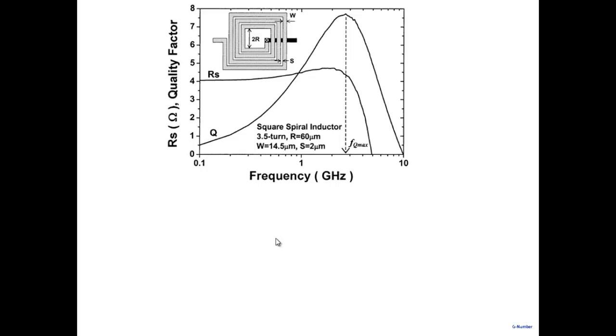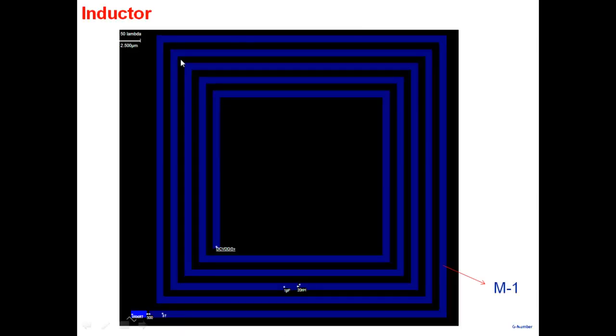Now try to recollect inductor. A pure inductor, any inductor will come with what? Parasitics and resistors. And it may also come with capacitances. It may come with capacitance, because note, if I'm using a metal one to make a spiral, where is this metal one sitting? On top of silicon dioxide. And underneath the silicon dioxide is what? Substrate. So I have a capacitance associated with it. So that's a major problem. I don't get a pure L. Along with it, I get parasitic capacitances here.